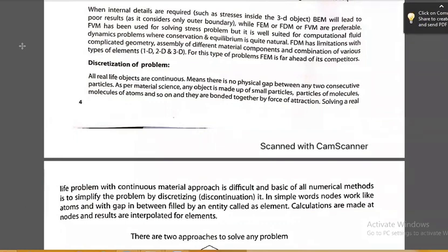Then next one is buckling stresses, for short members or long members. So this can be distinguished or defined depending on the third parameter. What will be this third parameter? It is nothing but the plane on which it is acting. So to define the stress we need three parameters. First one is its magnitude, second one is its direction, and third one is the plane on which it is acting. That's why stress is a tensor quantity. Okay, so this is about stress.